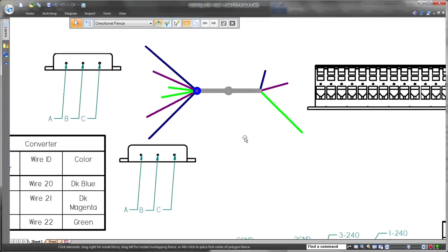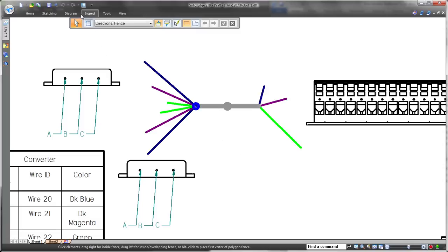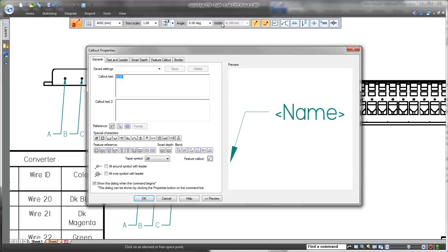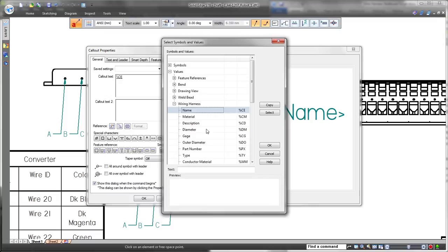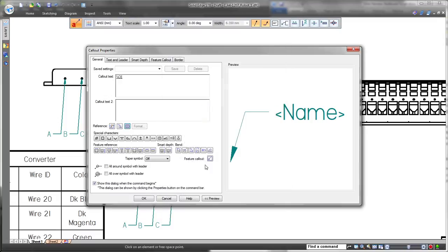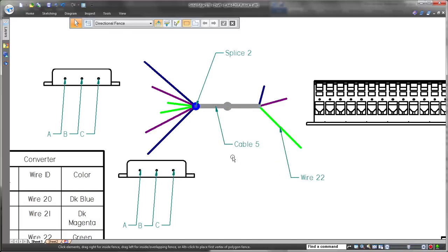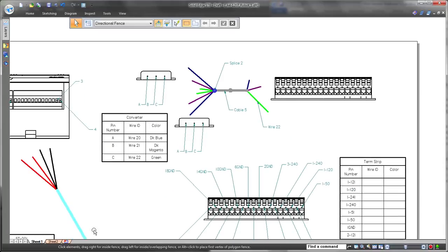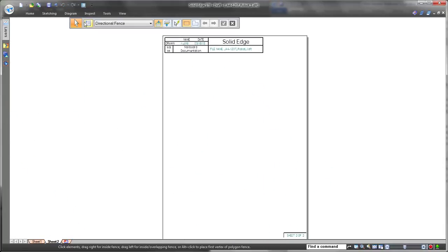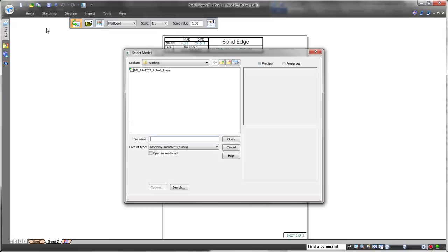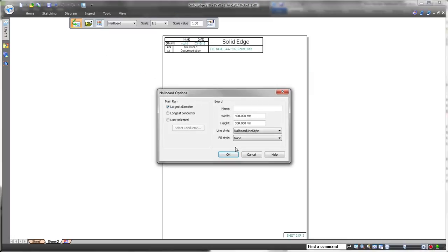Documentation of a harness's cables and bundles leverages Solid Edge's industry-leading drafting functionality. Here we'll finalize our electrical design by updating a nail board drawing. Solid Edge provides true nail board representations for layouts and connector tables. ST8 introduces splice representations on the nail boards. Watch as we place a callout to show the definition of the bundle and its corresponding splice.